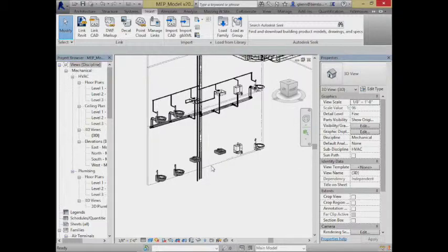It tends to be a different size for each of the different units. Big old commercial toilets tend to have a 4-inch out. Something like a urinal doesn't need to be as big as the 4-inch out because it's not carrying away solid waste, it's all just liquid waste. So those tend to be much smaller, maybe 1.5 inches. Even for the sink, it's probably 1.5 inches.